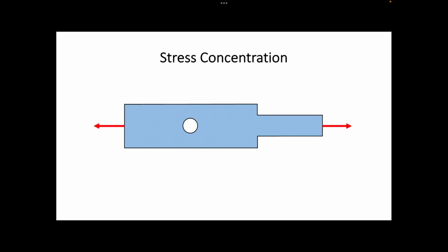Now let us study something called stress concentration, which refers to the increased level of stress at a certain area or location in a solid body. If you remember when we studied Saint-Venant's principle, we saw it already, where the stress near the point of application of concentrated load is very high. The thing we would like to discuss in this lecture is that stress concentration also occurs at the location of sudden change in the geometry or material of a member.